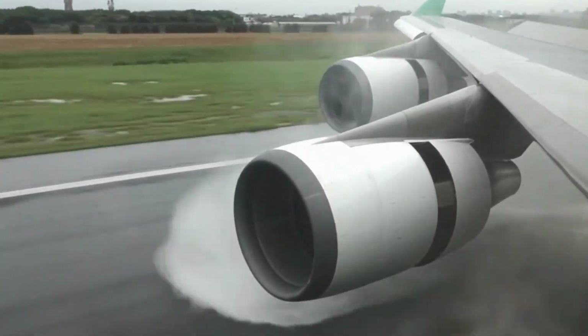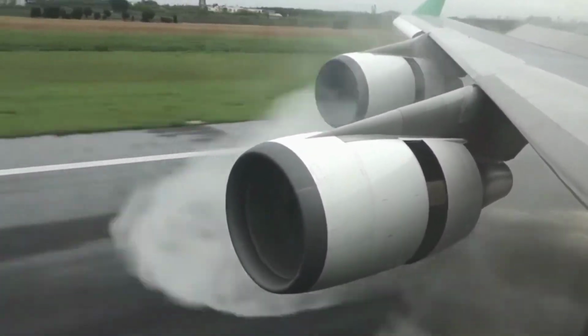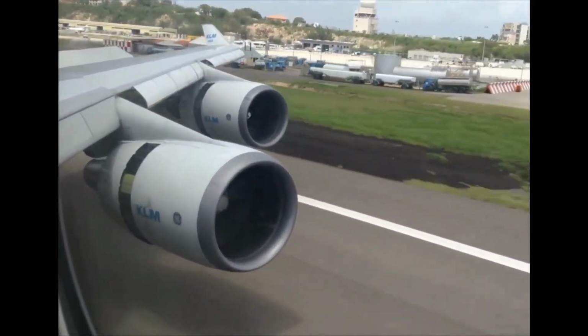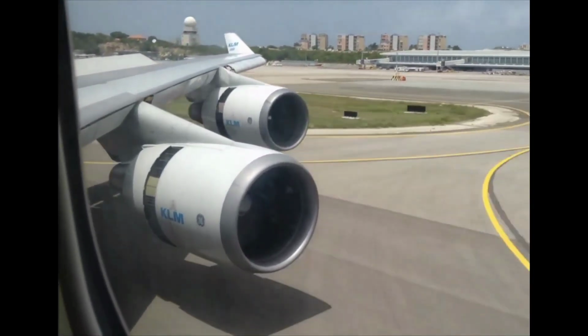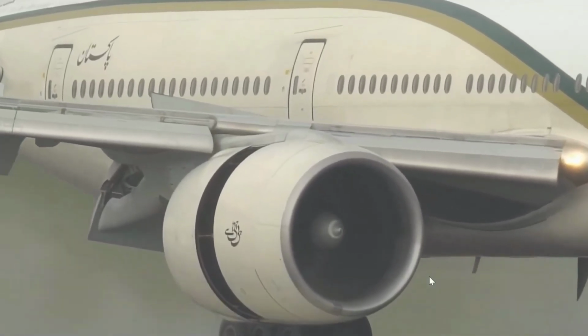Cascade reverse thrust is a common jet engine system that redirects airflow forward to help slow an aircraft after landing, using a sliding outer cowl to expose cascade vanes and blocker doors that turn the bypass air outward and forward, providing powerful braking assistance, especially on slippery runways, without overstressing brakes.